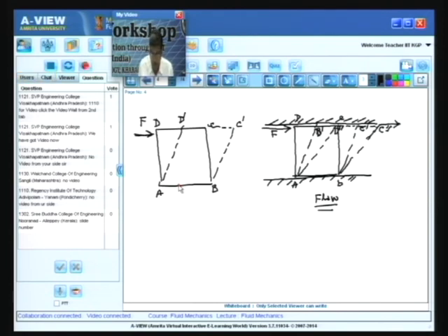Now, here another important thing is that even if this force is very small, however small it may be, even infinitesimally small, the continuous deformation will take place. The implication of this is that there are certain classes of substances, or you can say certain classes of solids, which after a threshold value of this F go on continuously deforming and behave like a fluid.